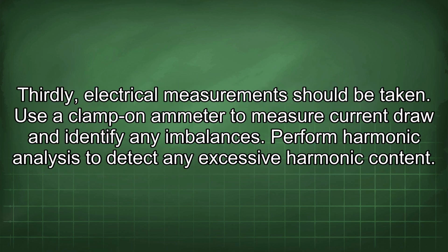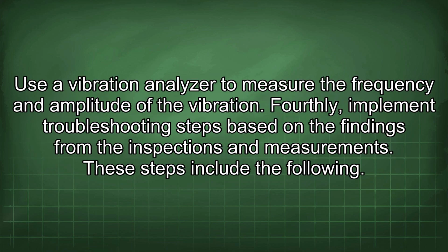Thirdly, electrical measurements should be taken. Use a clamp on ammeter to measure current draw and identify any imbalances. Perform harmonic analysis to detect any excessive harmonic content. Use a vibration analyzer to measure the frequency and amplitude of the vibration.